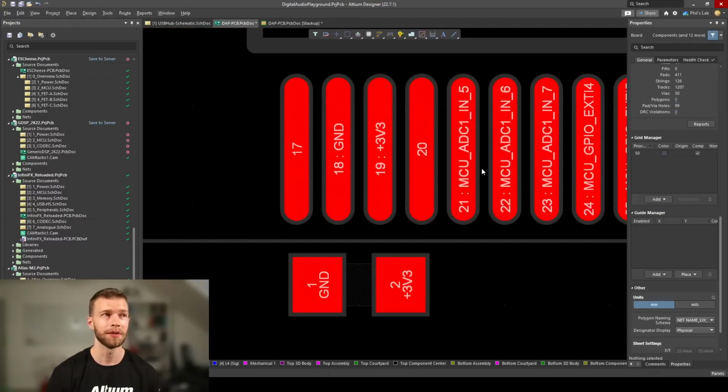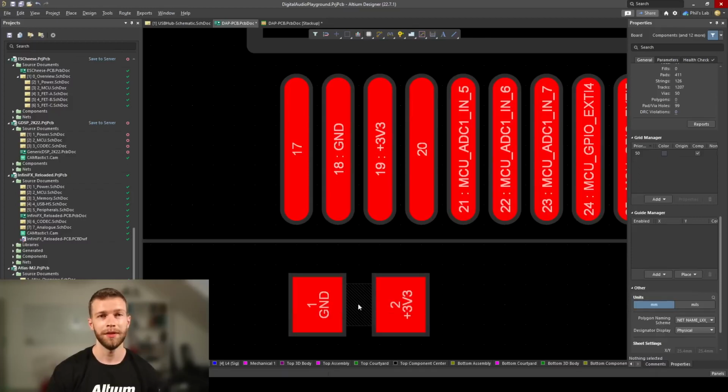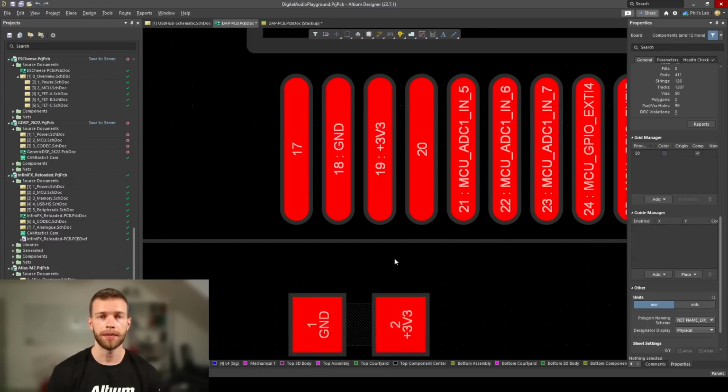And this can, of course, become quite difficult, and it becomes a challenge what to prioritize. Typically, for low-speed designs, you will have routed power and a dedicated, or at least one dedicated, ground plane directly below the IC. This way, you can drop a via below and then route power. If you then also have a dedicated power plane, in this example maybe a 3.3 volt plane, we can place vias between the component's power and ground pins and this decoupling capacitor, so we also get the benefit of the capacitance of the plane.